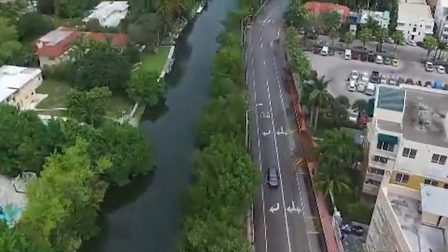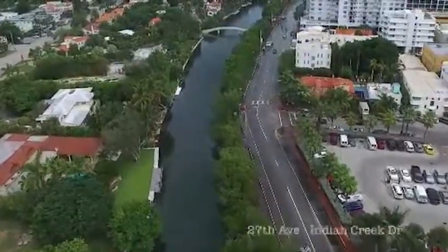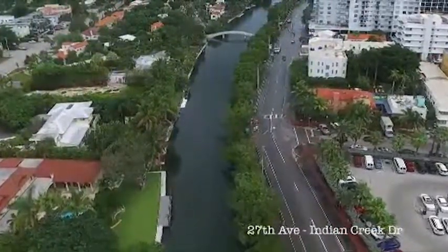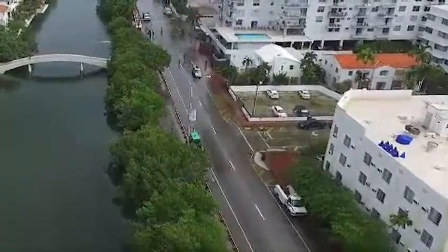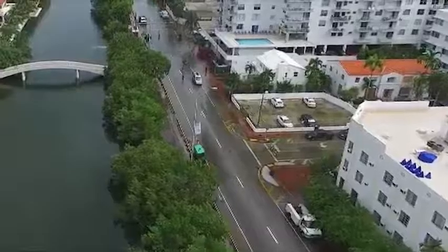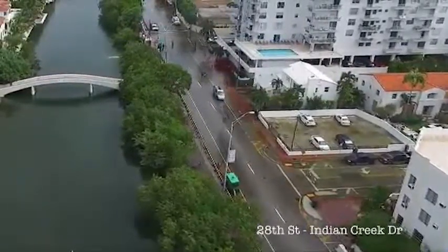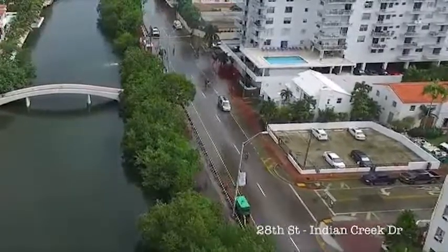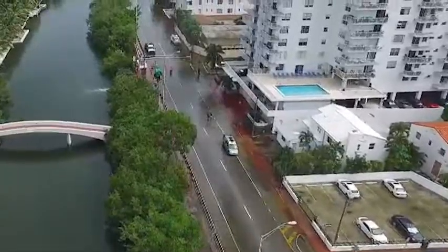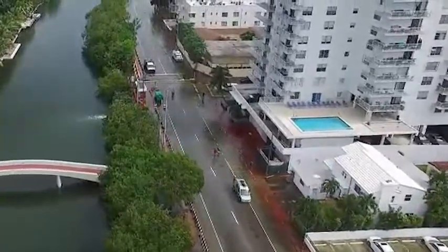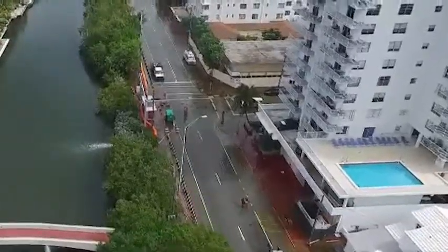So right now we're working on a high priority project that will involve reconstructing Indian Creek, raising the profile at least 1.5 to 2 feet, plus providing a 72-inch trunk line along almost a mile stretch of this roadway facility, plus a 50,000 gallons per minute pump station located right across 32nd Street. As you can see in the video, that's where the major flooding started, at 28th Street.